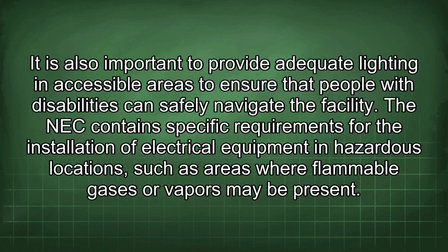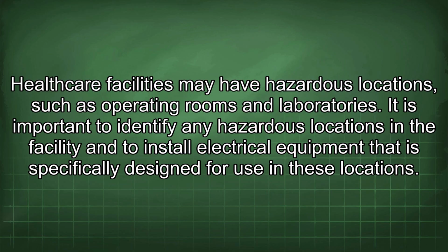The NEC contains specific requirements for the installation of electrical equipment in hazardous locations, such as areas where flammable gases or vapors may be present. Healthcare facilities may have hazardous locations, such as operating rooms and laboratories. It is important to identify any hazardous locations in the facility and to install electrical equipment that is specifically designed for use in these locations.